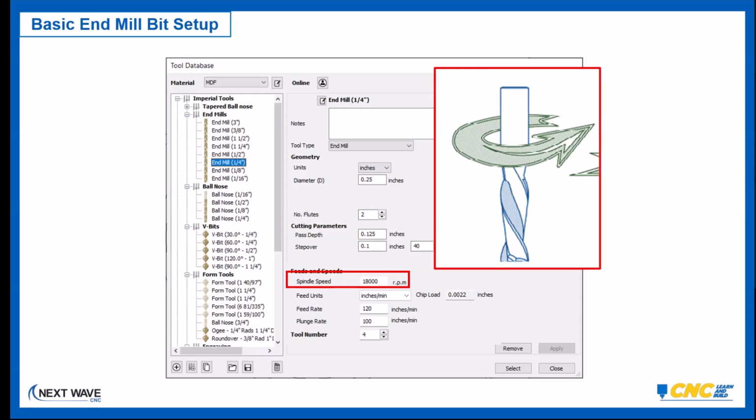Now, if I have another tool path that uses a different spindle speed, when the program gets to that tool path, it'll change to that speed. So it's very convenient having that setting in here. If you're using a woodworking router, or one of the smaller tools that uses a little trim router, then you have to set your speed manually at the router.